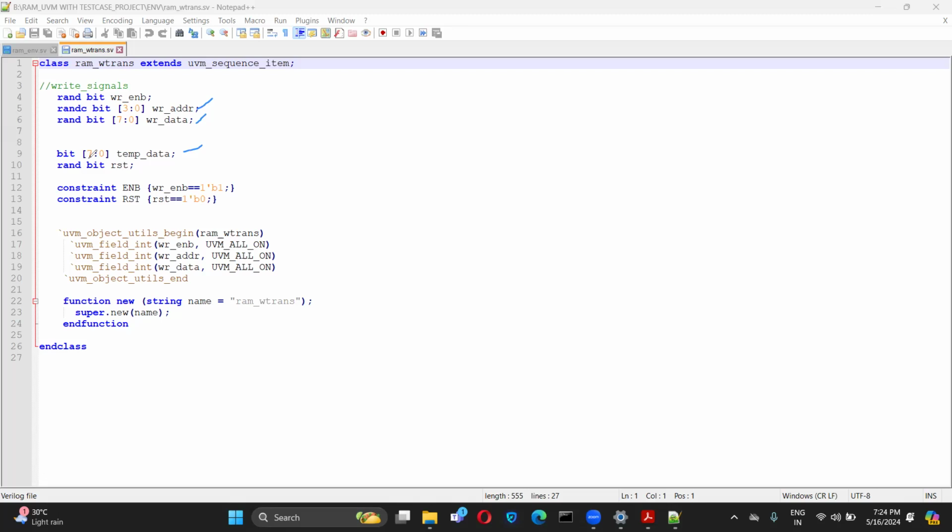So when there is an adder, you will give A as 2 and B as 3. Whatever inputs you are giving through the driver will go to the design, so they will be applied on the design. In the design you will have some logic, right? Inside the design, there is y equal to A plus B. So Y will be evaluated by taking the inputs which we are giving from the driver, that is A and B, from the entire transaction.